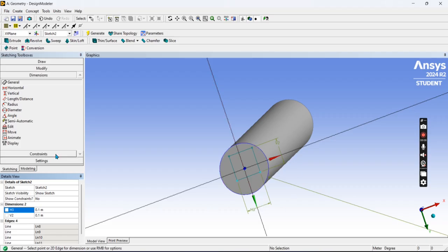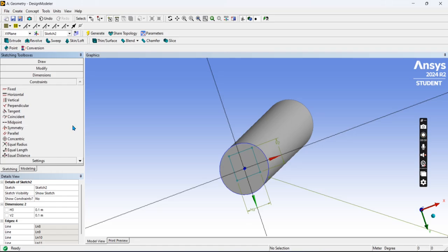To do that, go to the constraint section, which I mentioned earlier. That constraint section will make relations among two or three parts actually. So let's go to the symmetric section. We'll see symmetry right here under the midpoint section. Click that. Then firstly choose the axis along which you want the square or rectangle to be symmetric. So first let's select this y-axis, and the sides that will be symmetric along y-axis will be this side and this side. So now we will select that accordingly.